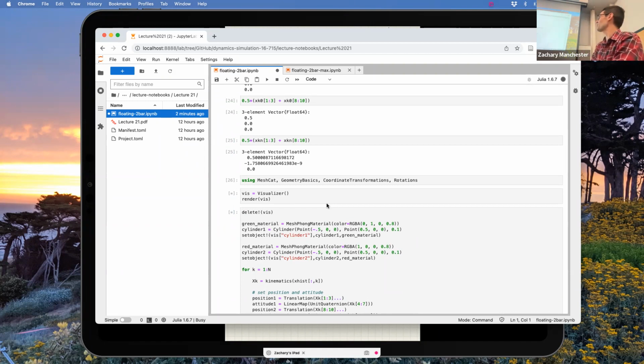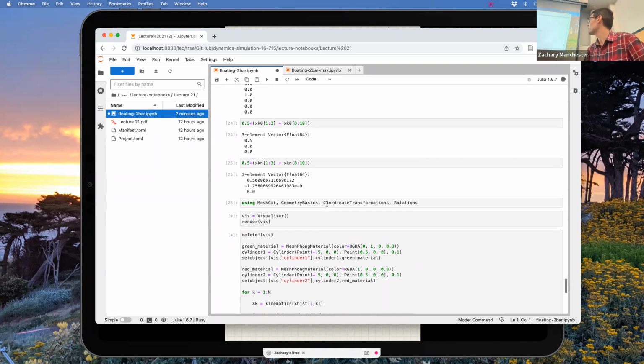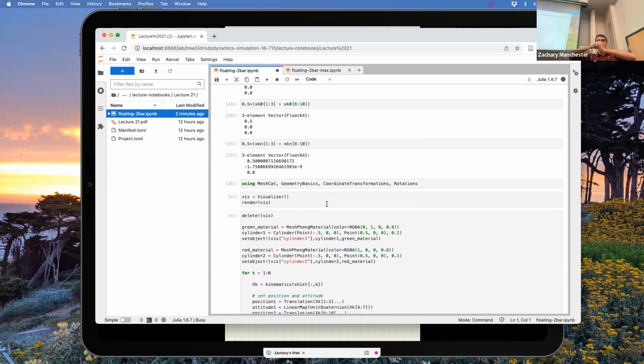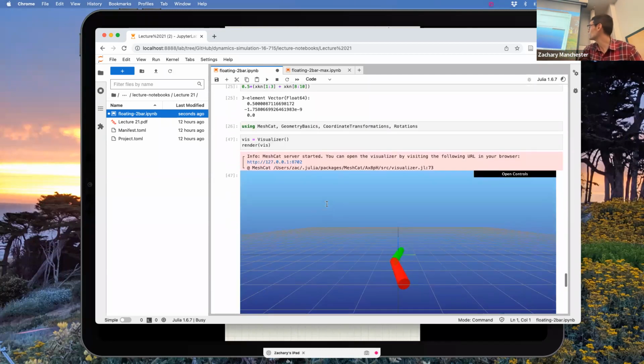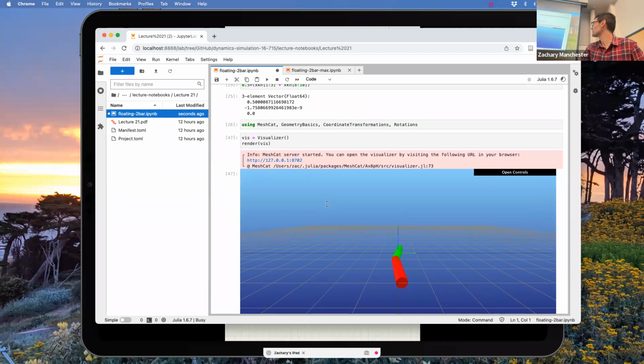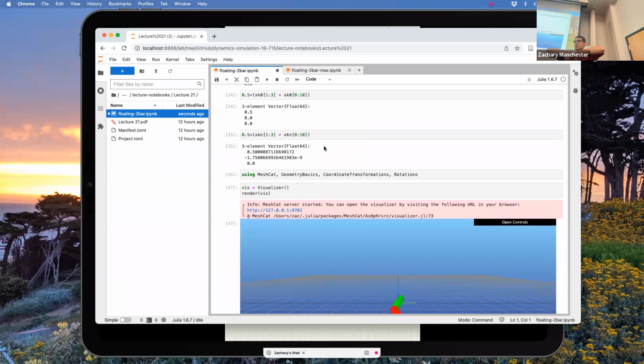Let's talk about one other little fun thing in here. This thing's floating in space. I'm only applying an internal torque at the joint. I'm not applying any external forces and torques, right? So there are all kinds of conserved quantities in this problem: momentum, energy. One of the conserved things is the center of mass position for the whole system. I'm not applying any external pushes on this thing, only internally between links. Oh, here we go. It wiggles back and forth, yay. Nothing surprising or very exciting about this. So the center of mass of the whole system can't move, because I'm not applying any external forces to the whole thing.